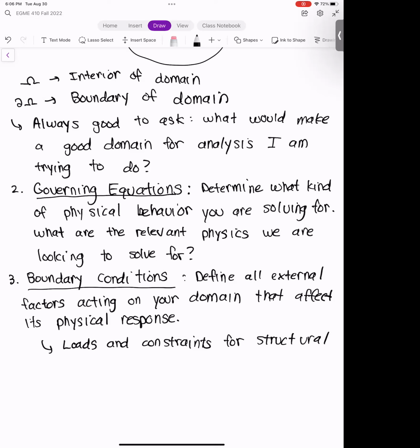And so there's a lot of variation that can occur in the boundary conditions, depending on the physical situation, and it has a huge impact on your results, right? As an example, for the ANSYS activity we did last week, if you remember, we applied a fixed support on the left side of the plate, and we applied a tensile force on the right.